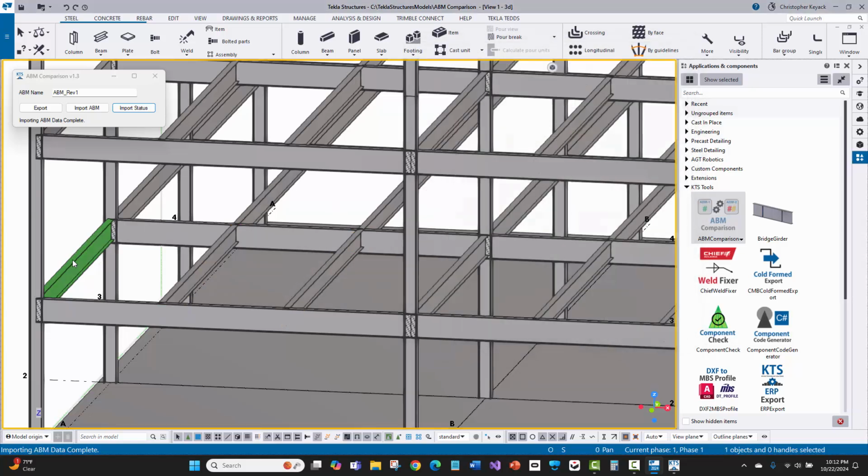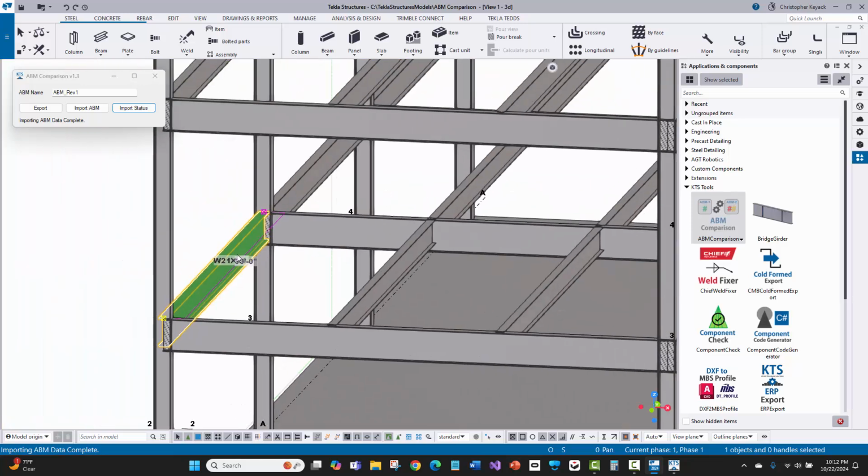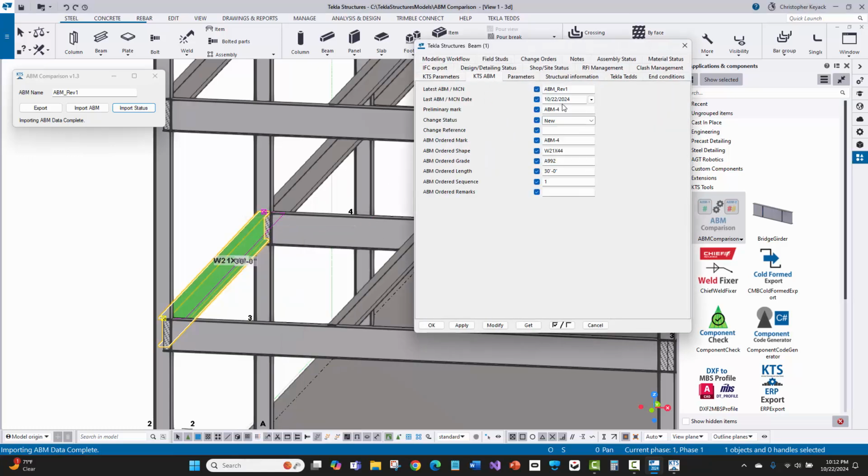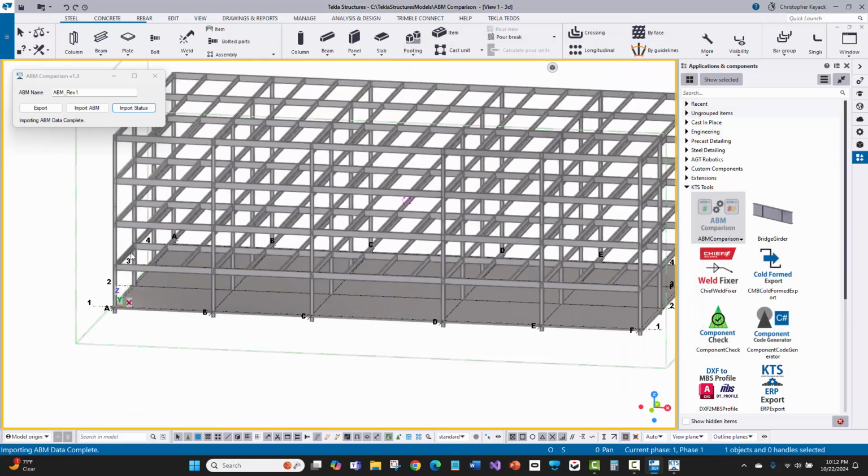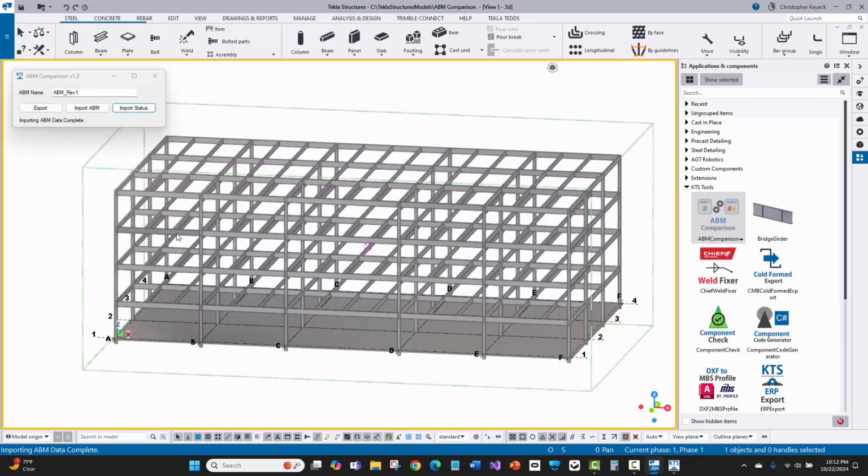And then the next thing I might do is just say that I've processed this so I don't get confused on the next go round. I'm going to come in here and go to user defined attributes. And if this particular piece, I notice that it's new and I verify, yep, that's correct, it's new, then what I can do is I can actually just turn this off here and just say modify, so that goes away. And now I have basically all my statuses cleared out.